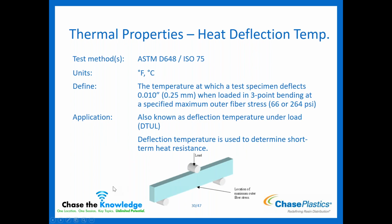So now we'll start talking about some thermal properties, starting with heat deflection temperature. The real scientific term for it: it's when it deflects 10 thou of an inch when it's loaded in 3-point bending at a specific outer fiber stress. So you'll see on a data sheet there are generally 2 different conditions, either 66 PSI or 264 PSI, also known as 0.45 MPa or 1.8 MPa. So the different loadings are the different conditions for this particular test. This is also known as heat deflection under load. So if you see DTUL referenced somewhere, just note it's the same test, just with an updated name. And then deflection temperature is a really good indicator of short-term heat resistance.